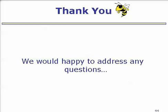Professor Cheming Wang is doing work at University of San Diego. He's made a good argument that for a lot of these types of frames, essentially an elastic seismic approach is probably justified. But if you get things like heavy hard walls, tilt-up walls in there, then you can't get it to work that way. So as far as the research side, I think the jury is still out on how best to improve on those things.